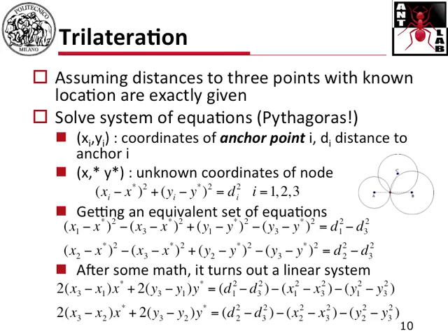So basically, the di's measures are what the localization system gives you, provided some kind of sample in terms of received power or time of arrival measured. Then you know where the anchors are, so the xi's and yi's are the positions of the anchors. And what you want to enforce is that the distance from anchor i to the reference point, which is x star here, is exactly equal to the distance which is measured by the localization system.